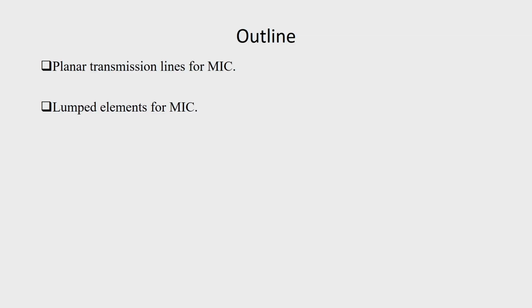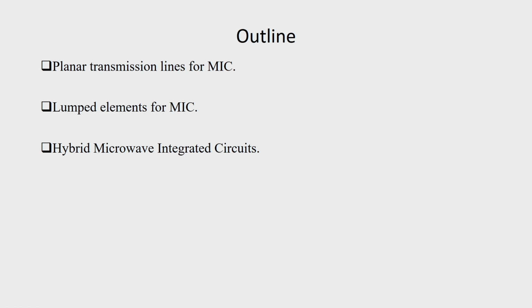And then we will see the lumped elements for MIC. Here we have the resistors, the capacitors and the inductors in the lumped form, that means size very small compared to the wavelength, and which are suitable for integration with other circuitry fabricated using planar technology.